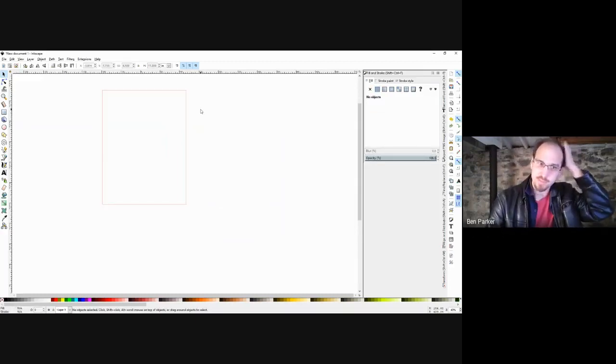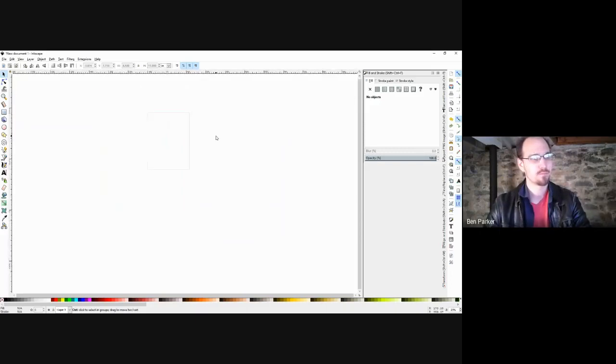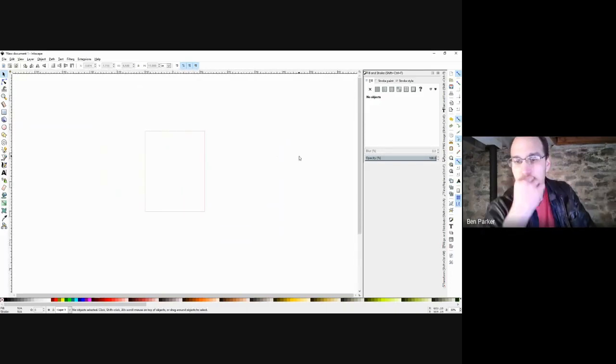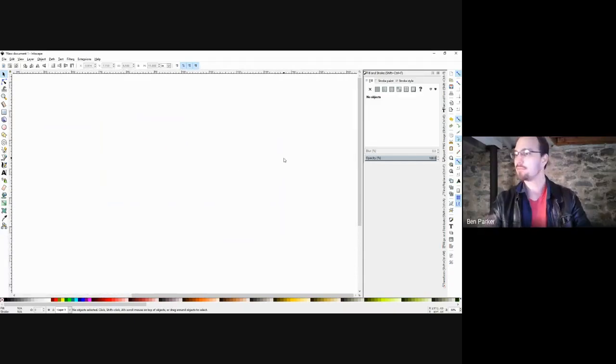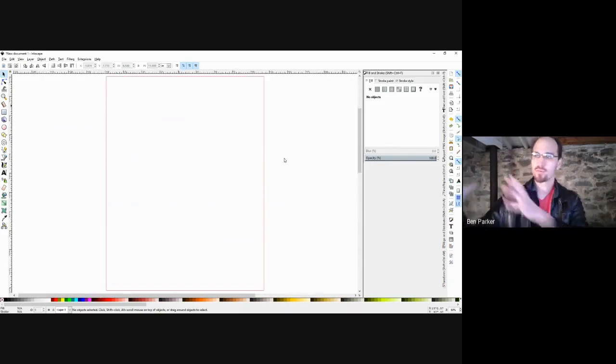You don't have to do this. It's just so that you don't get lost. And as you're moving around playing with these, you might end up, say, off the screen a little bit. A good way to bring it back to base is to press the number 4, and 4 will snap directly to the entire boundary of the drawing. Okay. For other movement things, you can press the plus or the minus sign to zoom in or out.